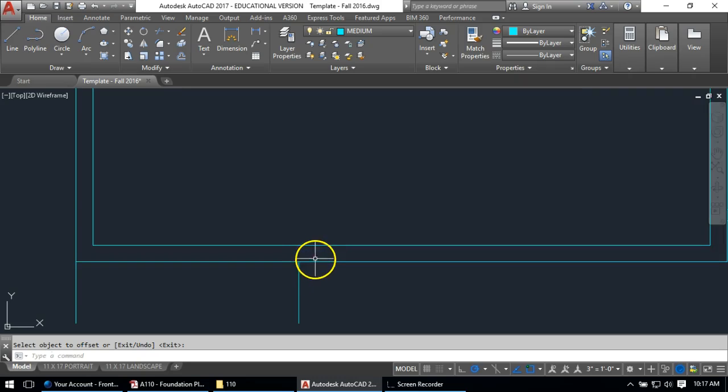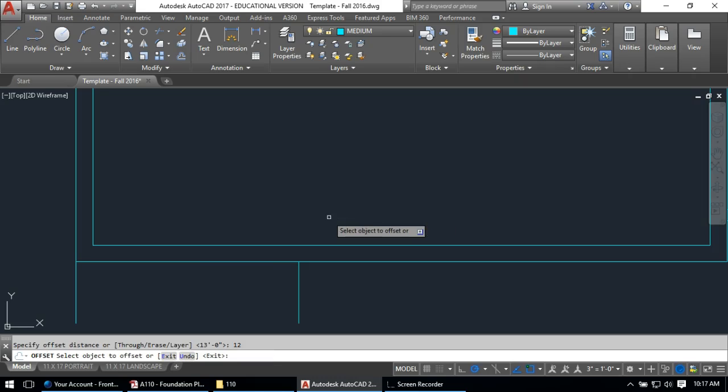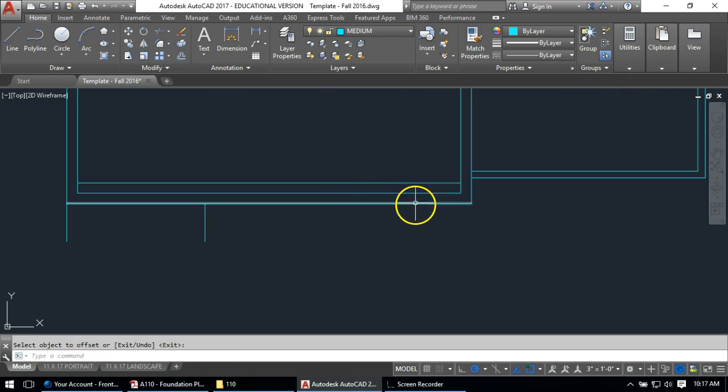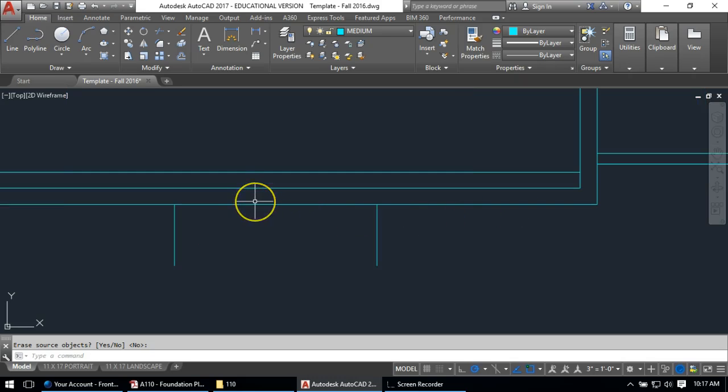And then obviously it's offset 1 foot, but so is the wall, so the front is going to be up here, and then the back is going to be another foot back. So I can start by offsetting that another foot, or 12 inches, and that'll just give me a line there. And then the 13 feet is offset on the other side, so I can actually use mirror from the midpoint to get the second point here of a guideline, although I could have drawn the same thing, offset at a 13-foot line that way as well.